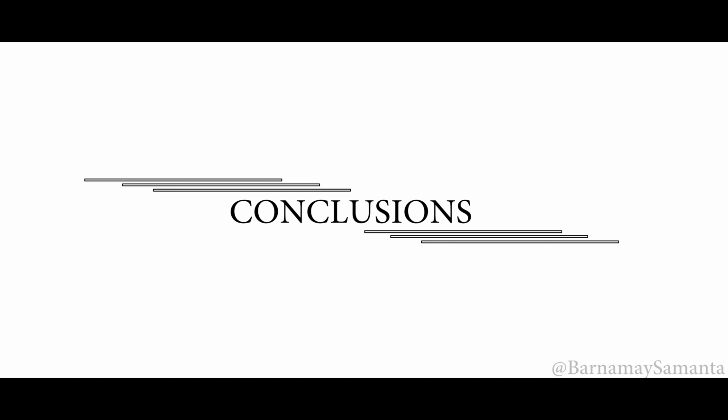Flow structures of impinging jet on protrusion target surface are not sensitive to protrusion relative depth and impinging jet Reynolds number. The jet turns its flow direction as it impinges onto the protrusion. Then the flow separation occurs when flow passes through protrusion edge region and at the same time secondary impinging jet forms.